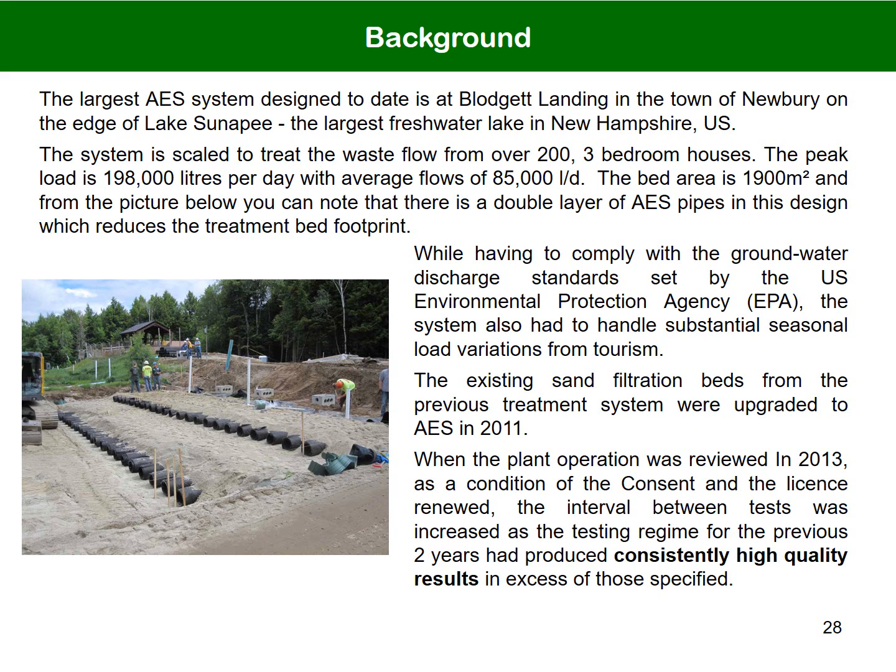The largest AES system designed and installed to date is at Blodgett Landing in the town of Newbury on the edge of Lake Sunapee, the largest freshwater lake in New Hampshire, USA. The peak load is 198,000 litres per day, with average flows of 85,000 litres a day. That can be compared with the flow from a 3-bedroom house, which is around 1,000 litres a day. So this system is designed to cope with a flow of in excess of 200 3-bedroom houses. The system bed area is 1,900 square metres.